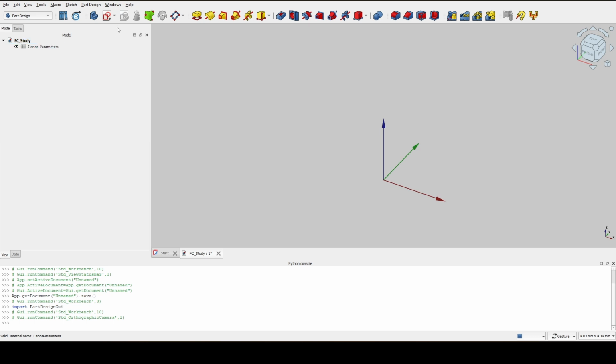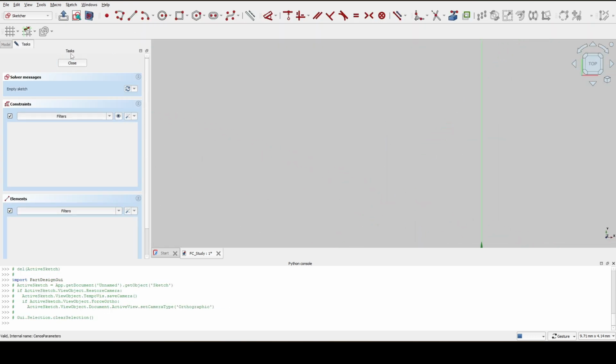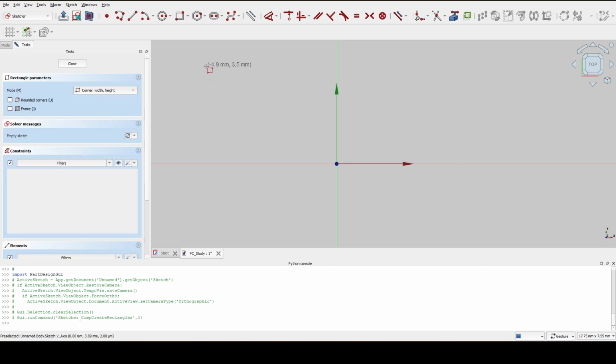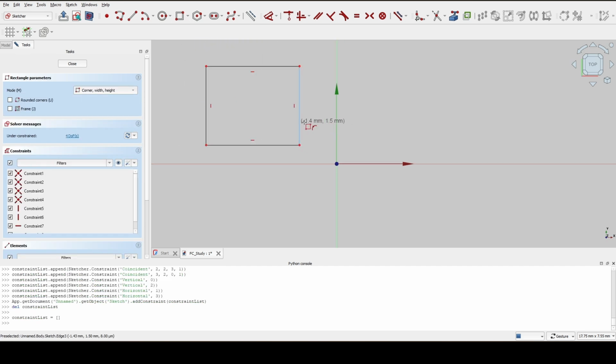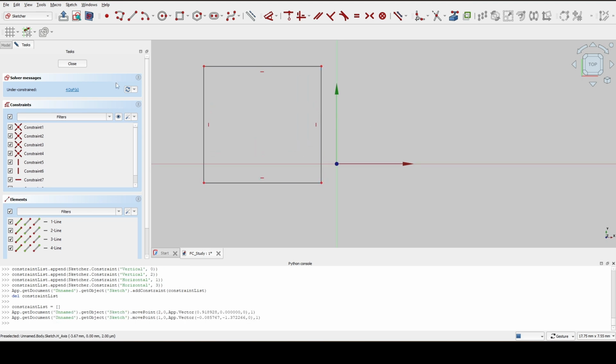By default, FreeCAD opens in the Part Design workbench. You can easily click Create New Sketch, choose the sketch orientation, and click OK. Now you can begin drawing. The upper toolbar offers various drawing tools and constraints to define line quality, the dimensions, and more. You can also dynamically draw and reposition your sketch. Once done, click Close to exit the sketch mode.